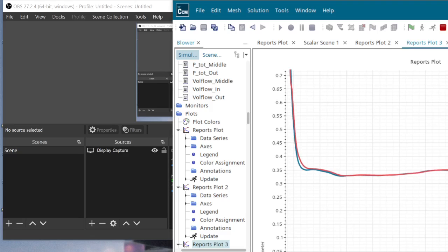So, to give you an idea of what I mean by really close, you probably want to look for an I value so that this volumetric flow rate, let's call it the min value, is approximately, let's go with 5%. This should be an equal sign. V min is 5% of V max. Basically, you want to get this small enough.